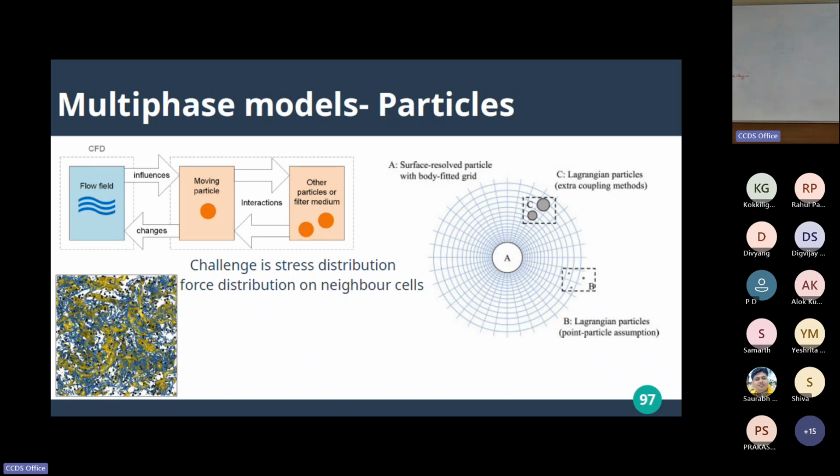Maybe, for example, some abstract turbulent flow field is there, some zoomed-up view of maybe a combustion chamber, with some black dots. Those are the particles. The turbulence interacts with the particles. If I want to simulate that, first one has to decide what kind of turbulence you are trying to model and what kind of length scales are involved. If the length scales in the problem are way larger than the tiny particles, you purely go with an Eulerian flow field with Lagrangian particles.